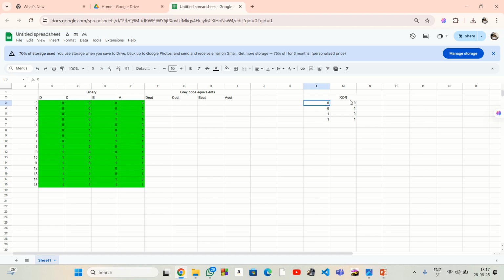It shows true values for different inputs. In this case, the inputs are the same, 0, 0. Therefore the output is not going to be 1, but it's going to be 0. And here we have 0, 1. Those are different inputs, therefore the output is going to be 1, because it's a true value representing different inputs.